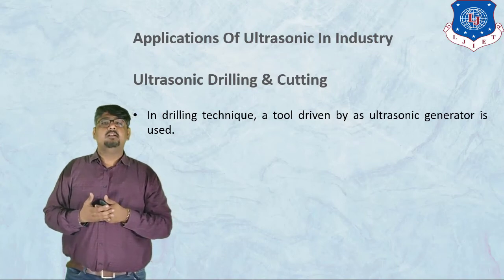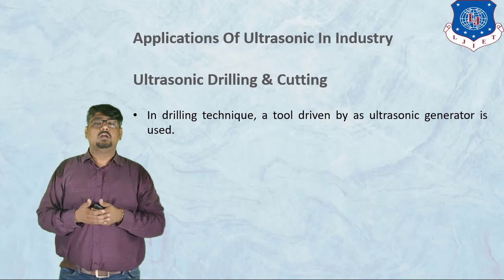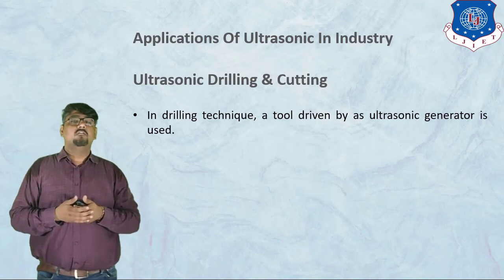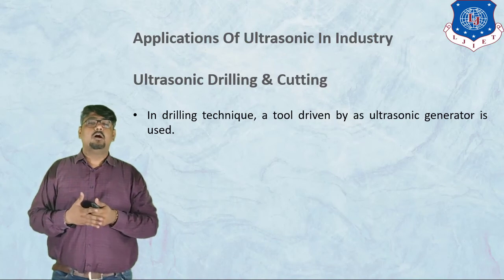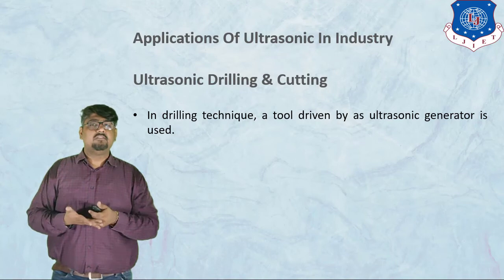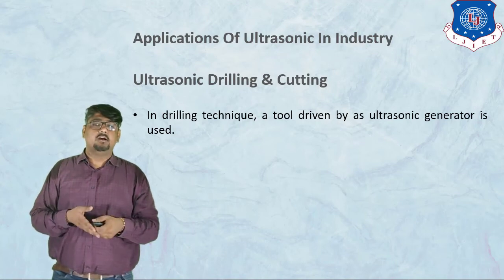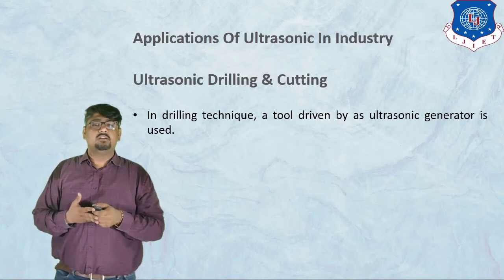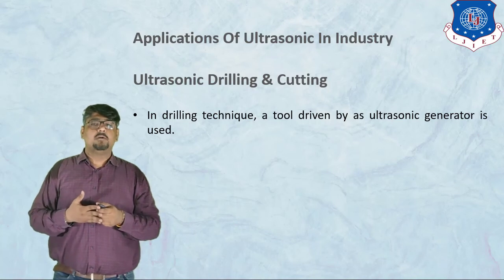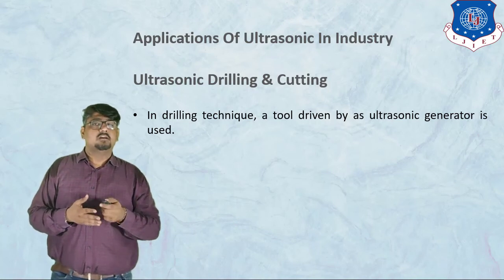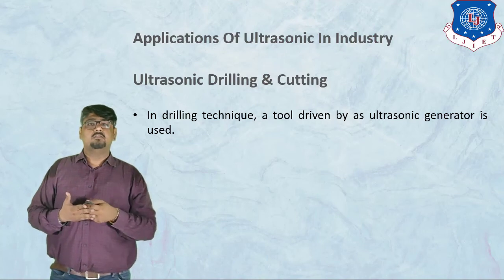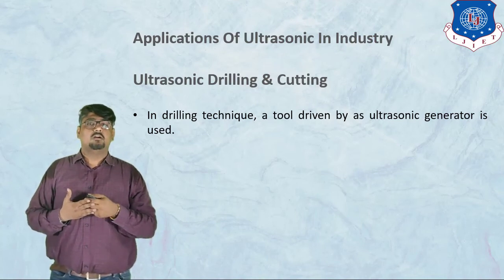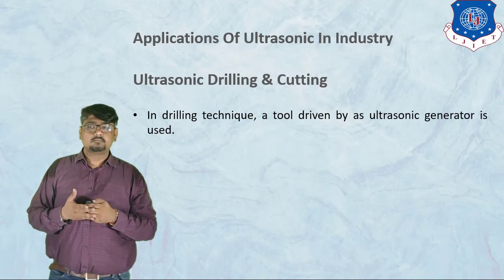You might know about them. An abrasive is a material that is used to sharpen or finish a sample by rubbing, which leads to a part of the sample being thrown away. That is the definition of abrasives. So here we are going to use abrasives such as boron carbide or silicon carbide. Carbides are very hard materials, so they are used here for cutting metals.